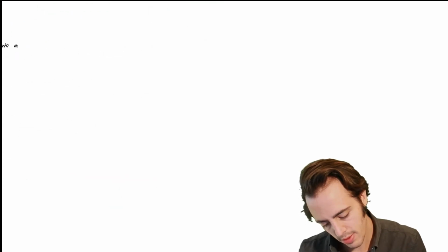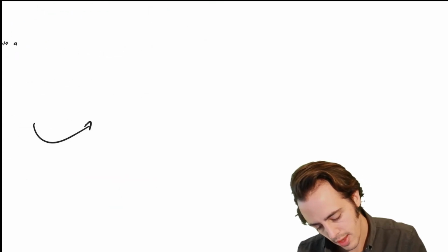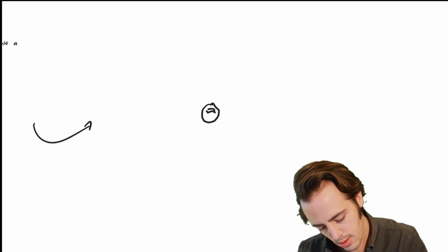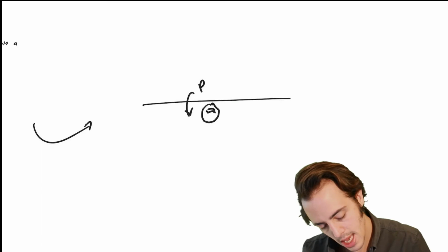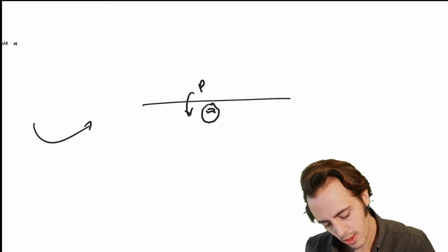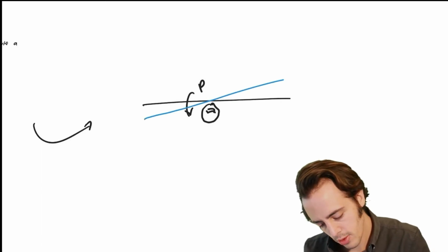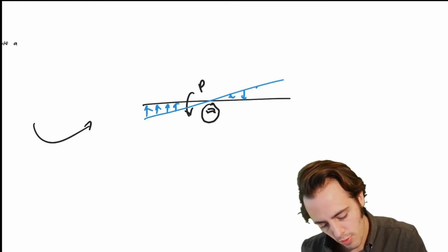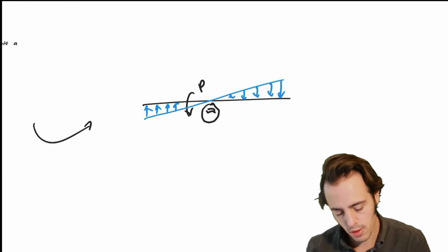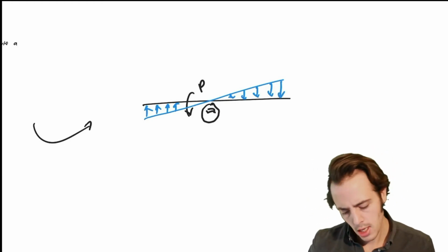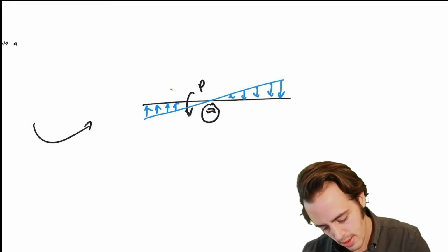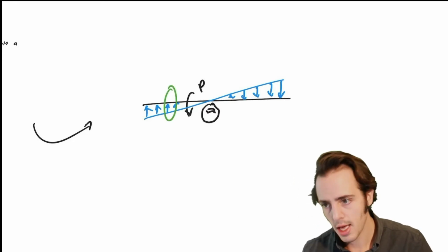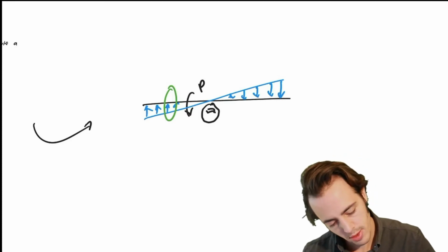If we're not certain about that, let's just remember that if we looked at this aircraft from the front, we've got a wing here, this aircraft is rolling with roll rate P, then there's going to be a velocity field that is proportional to both the position along the wing and the roll rate. Okay, so this is just from the motion of the wing itself. So if we take a section of this wing, let's say take through here, then let's just remember our coordinate system.